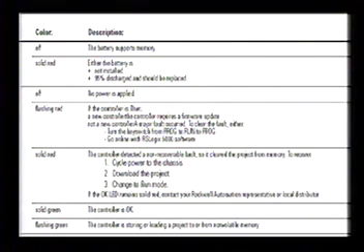If it's solid red, the controller detected a non-recoverable fault, so it has cleared the project from memory. To recover, cycle power to the chassis, download the new project, change to run mode, and if the OK LED remains solid red, contact your Rockwell Automation representative or local distributor. And so that's the key.